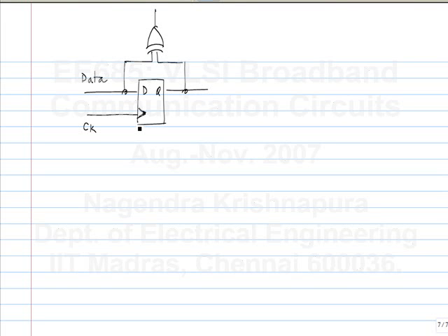What are the other problems with the XOR gate? The reference feedthrough will be high. Reference feedthrough will be high. Lock range is limited, but the lock range limitation we got rid of by going to a type 2 PLL. So we can do the same thing here. Okay? Still there is a larger AC waveform riding on the average. Why? No, anyway, let's continue this tomorrow. Okay? That's not the case.